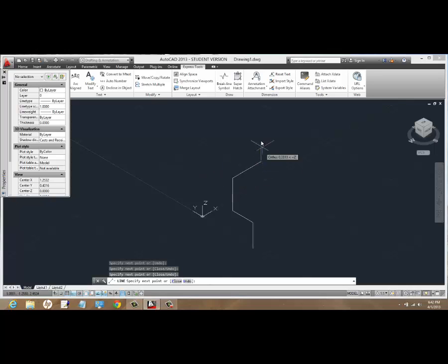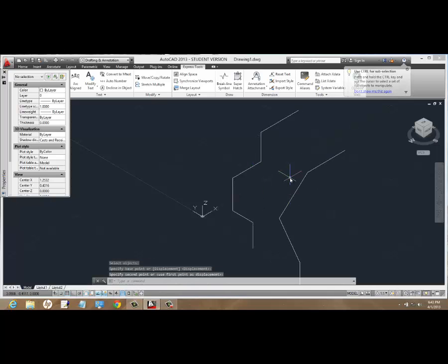Often I will draw a line sequence with the line command that would create multiple endpoints. You will be able to draw a line representing run, offset, and roll, which will later be used to accurately place the diagonal 3D polyline. When you do the 3D polyline, you go from the vertices to vertices of the lines, or endpoint to endpoint. Any way you draw a 3D poly is acceptable for this instruction though.